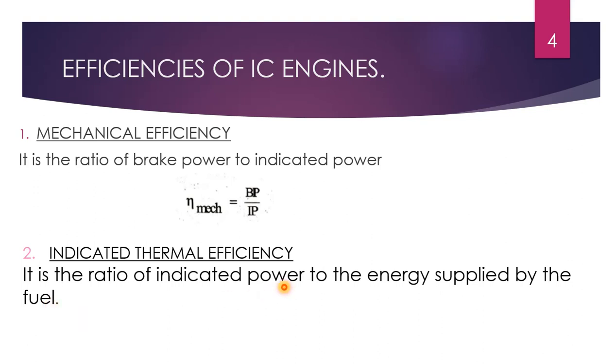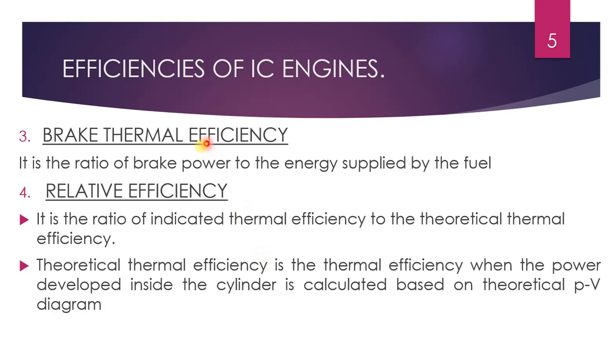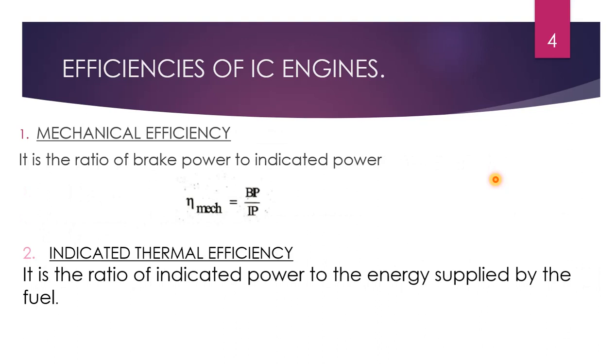And another efficiency is brake thermal efficiency. It is the ratio of brake power to the energy supplied by the fuel. So brake thermal efficiency is brake power to the energy supplied by the fuel. Similarly, indicated thermal efficiency is indicated power to the energy supplied by the fuel.